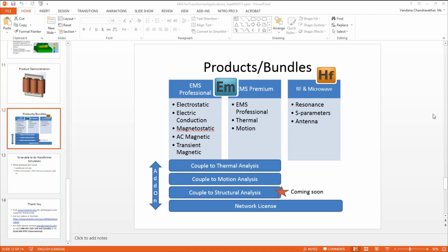One is the current that is there in the coil. That's called the winding loss, or the losses in the coil. That's basically the I squared R losses in the coil, and that leads to some rise in temperature in the coils. But the majority of the temperature rise that you saw in the demonstration is basically because of the induced current.